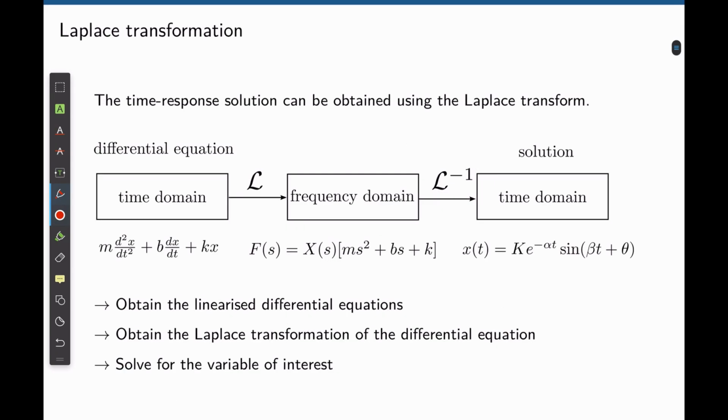Let's cover the basic principle of a Laplace transform. We start with a set of differential equations that represent the behavior of a given dynamic system. The objective here is now to solve for x of t, which is a solution to that differential equation. By applying the Laplace transform of a temporal response, we now get the so-called frequency domain response, and by solving for the inverse Laplace transform, we can find x of t, which is the solution to the time domain expression that we started with. From now on, we will always study systems in the frequency domain.